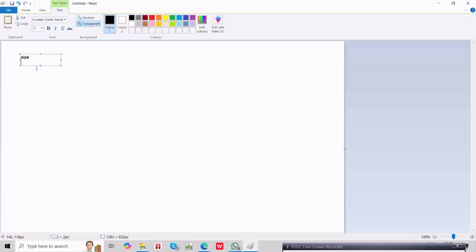Because when you go to a buyer, he's not going to give you a bevel end pipe or threaded pipe. Everything you have to make at the site. When you purchase it from the market, it comes with a plain end, right? Everything 2 inch and above goes for bevel end. Bevel end means butt welding. Butt welding means 2 inch and above. That is how we will study it, because this is important when you read your PMS, piping material specification.